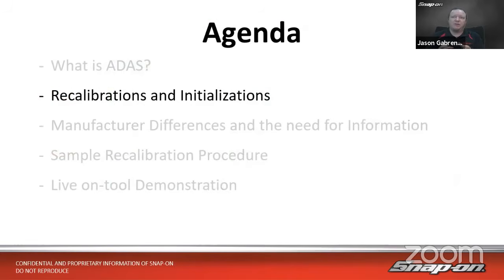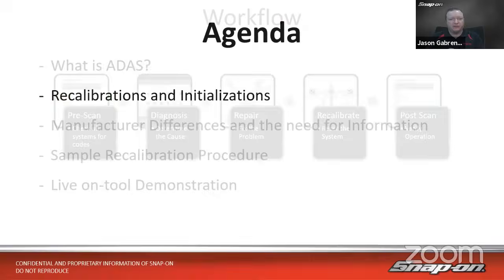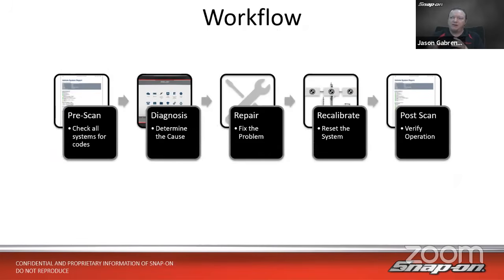So next, let's talk about recalibrations and initializations. If we think about a diagnostic workflow, and we're going through and repairing or diagnosing a vehicle, it's good to have a standardized workflow to kind of walk through. That way we don't miss any steps, right? So first off, we would like to do a pre-scan like we just discussed, right? We want to pre-scan on the vehicle, make sure we check all modules for codes.